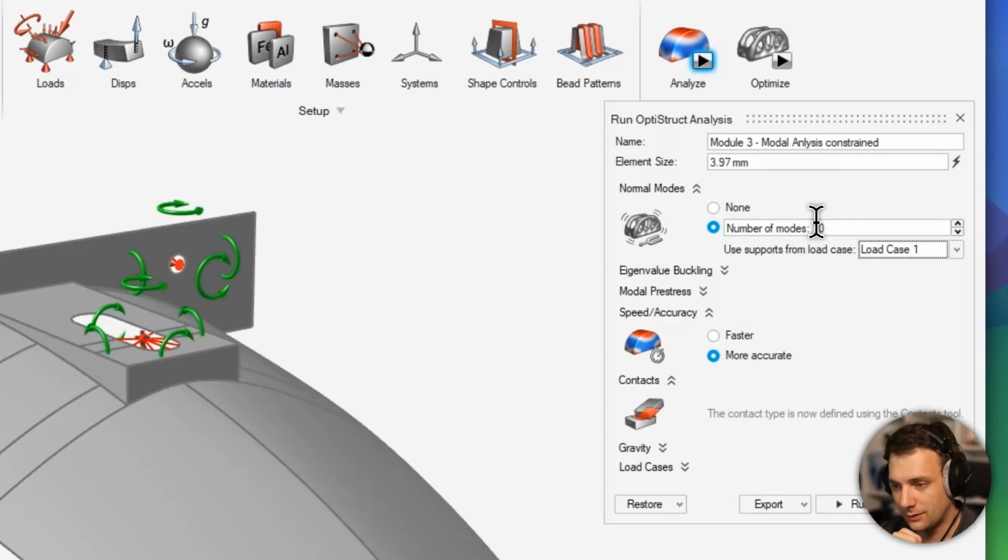But you have the complete mass and the effective mass. And if the effective mass, that means all the parts that are moving in the eigenfrequency spectrum, is close to the complete mass, then it's all right. So then you have selected enough modes. But that's another topic. We could go into a whole lecture on this, but we won't do this here. And I think that's all right.